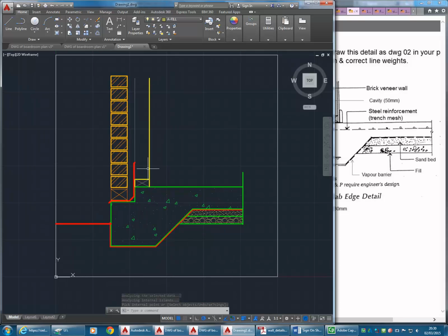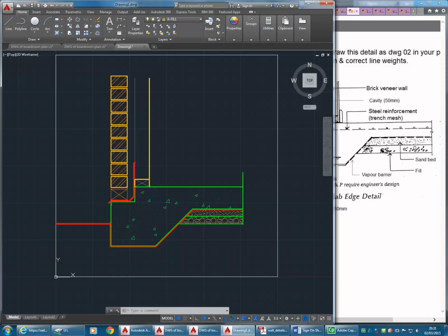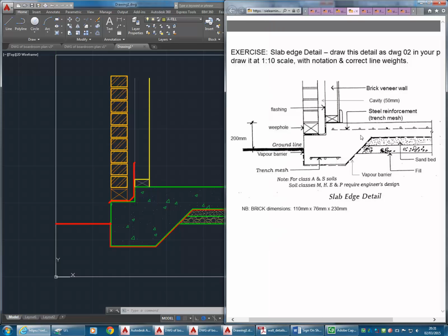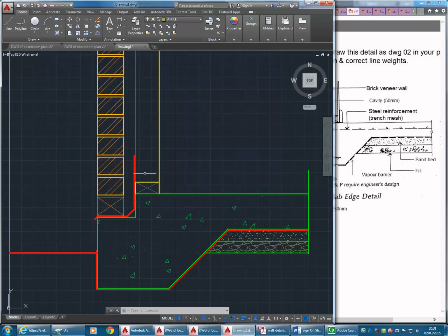So again with hatches just try to use your judgment for the size, but there is a logic to it. It's just not worth going too far into that. When you get stuff from America it's always interesting, but I'll just point out the scale factor. 25.4 is the number to remember when you try and change things from America, because that's the number of millimetres in an inch.